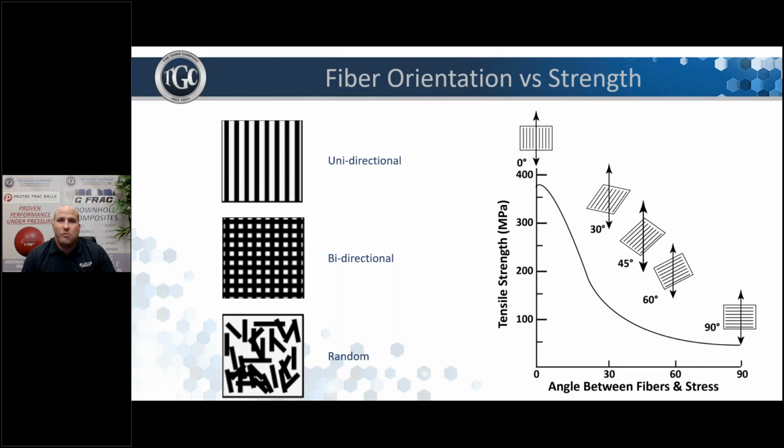Based on this curve diagram, we would expect that the tensile properties transverse to the zero fiber orientation would only be around 15% of the properties found at the zero direction. Random, bidirectional, and quasi-isotropic orientations should also provide about half to two-thirds of the tensile properties found in the zero orientation. A frac plug is a good example of parts utilizing different angles to improve certain property strengths. Even though you have components all going together on the full assembly, different parts utilize different wind angles or fiber orientation depending upon each component's function.